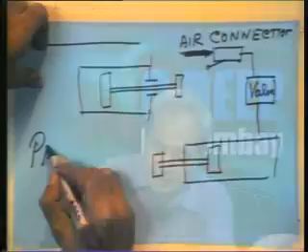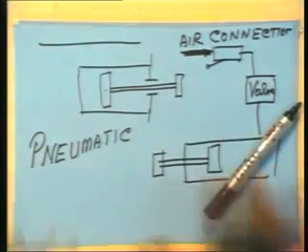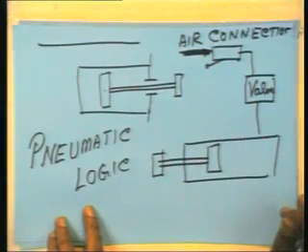Instead of using a separate electrical connection to this, both are mounted together. That means instead of an electric solenoid opening the valve, you use pneumatic pressure to open the valve. So pneumatic logic is used in these cases. Just like you have this breadboard, you can connect the various valves on that. Using that pneumatic logic, you can sequence the way you want, send the signal to the corresponding valve, and connect the valves through the pneumatic logic. Then you can avoid the electric. Then in the case of hydraulic ones, people have come out with fluidic logic.